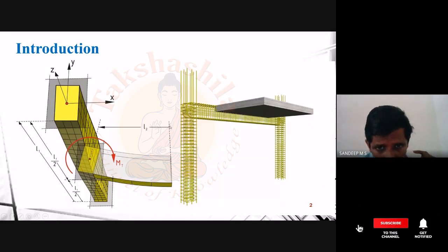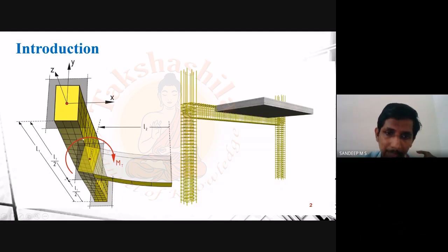But at the same time, if you look at this figure, this load is also trying to rotate the beam in a different manner, about this Z axis. The cross section of this beam is rotated, or twisting, along the direction of the beam. This is called torsion. Torsion is basically twisting, whereas bending moment bends the beam. Torsion will just try to twist the section.